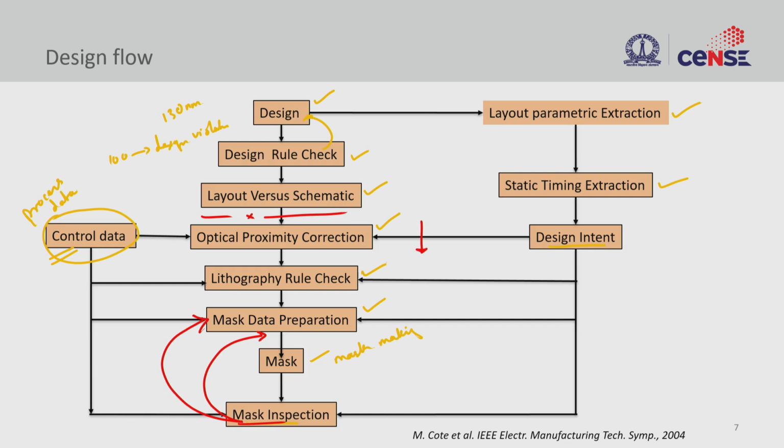But the interface here is this design intent, right. So what is the purpose of my circuit? You share this detail with the litho team, and they are going to use those data in order to do the timing analysis after doing proximity correction, or in some cases it is given back to the designer to run the timing analysis and also window and so on.